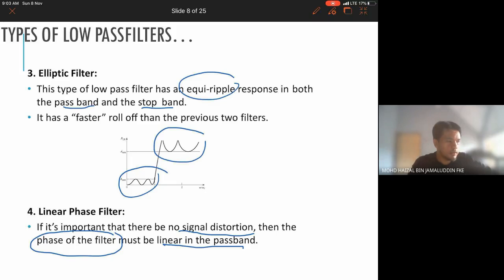The first one is the filter specification, which includes the cutoff frequency, the stop band attenuation, the pass band insertion loss, the pass band behavior, and etc. Second is the design of the low-pass prototype circuit.